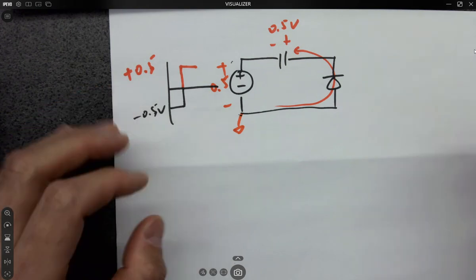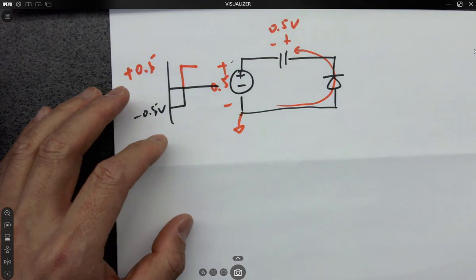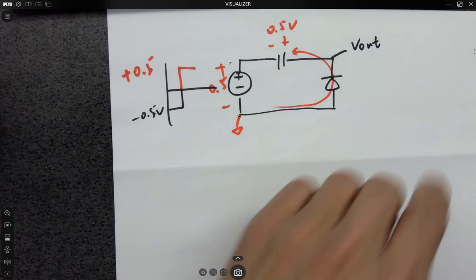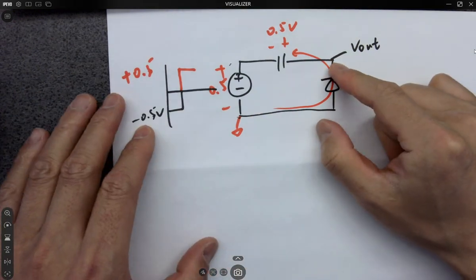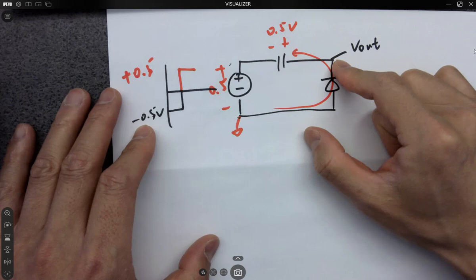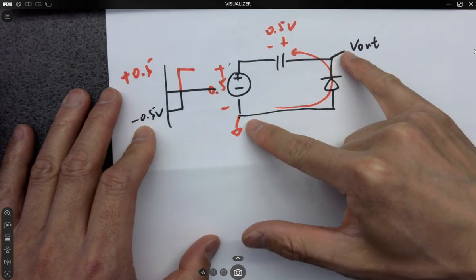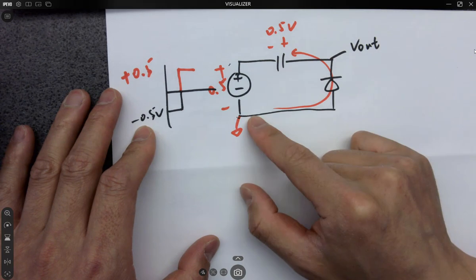So which means when you are probing, when you are looking at the voltage at the output, all the voltages are relative, right? But when I'm talking about the voltage at a certain node, I mean the voltage from here compared to ground, okay? So you have to know where's the ground first in order to look at the voltage output. So this is always ground.